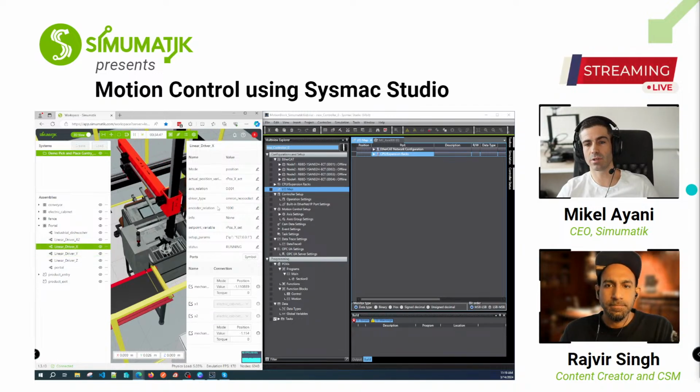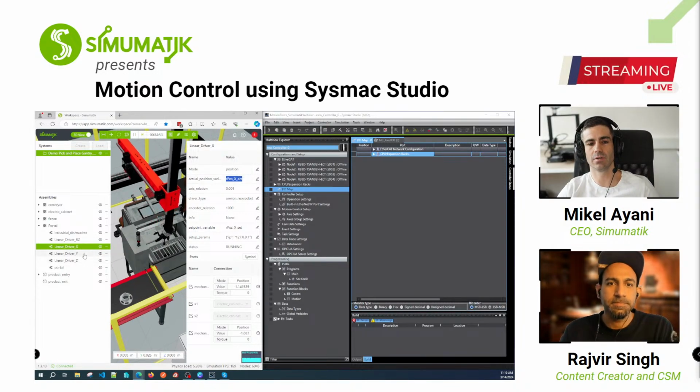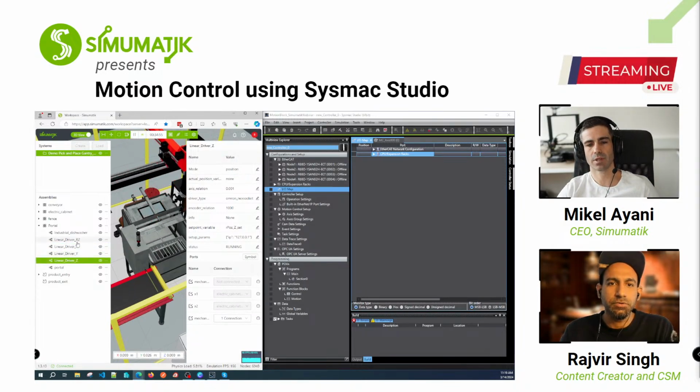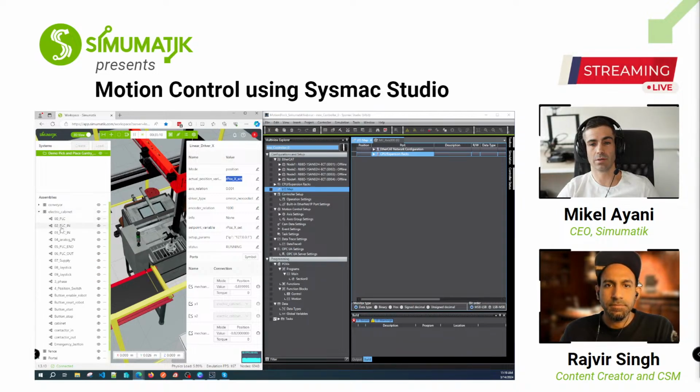As I can see, you have been experimenting with the x-axis to see how we can close the loop, but not with the other axes. No, not with the others. I just wanted to try. So here we can see that we are reading the set point from the PLC for all axes, but we are just sending the feedback, or the encoder value, for the x-axis. And that's basically all the configuration.